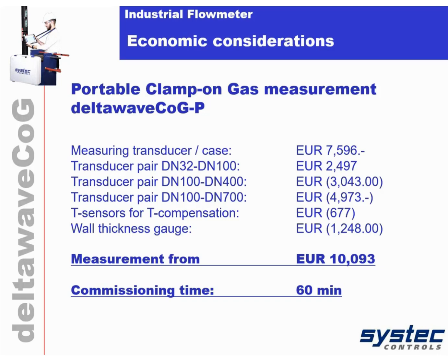Ideal application. The portable meter has analog and digital output, so it can replace an installed flow meter for the time being, if it's for calibration or repair, for example, or you can test meters. So a very interesting technology for companies like natural gas suppliers. They usually have those meters to check in the field or to replace their meter during calibration.